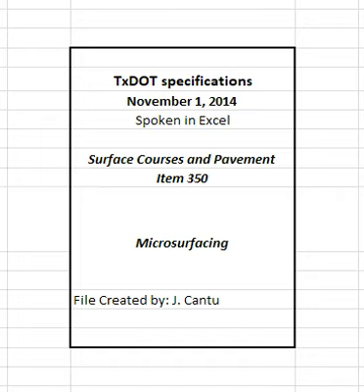4.4 Weather limitations. The contractor may pave any time the roadway has no standing water on the roadway surface, the roadway surface temperature is at least 60 degrees Fahrenheit and the ambient temperature is at least 50 degrees Fahrenheit and rising. Place mixtures only when the engineer determines the roadway surface weather and moisture conditions are suitable. The engineer may restrict the contractor from paving if the ambient temperature is below 60 degrees Fahrenheit and falling. Cease placement 24 HR before the National Weather Service forecast predicts temperatures below 32 degrees Fahrenheit unless otherwise approved.